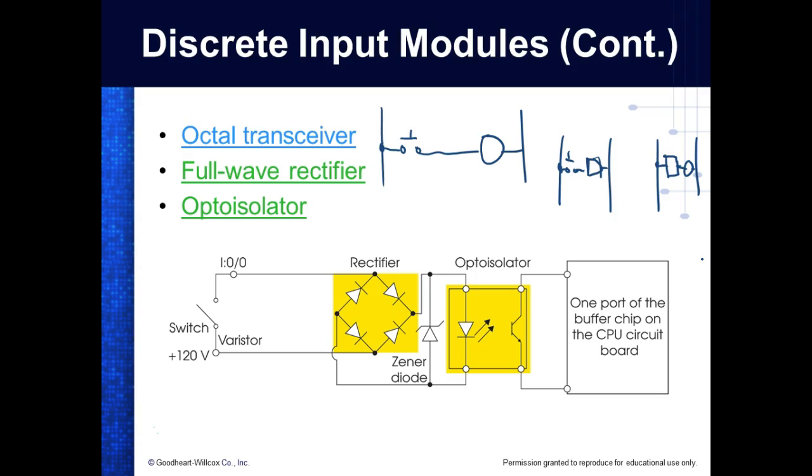So all these addresses that you're assigning are logical addresses, which is pretty neat. So I can change, so that means I got this contact up here. I can say I'm going to use input 3. Okay, well, no, I need to use that down here. So I'm going to make that 4. You just assign these things by addresses, which is pretty neat. And there's a little more to this, but basically we have DC inputs, we have DC outputs, DC inputs.